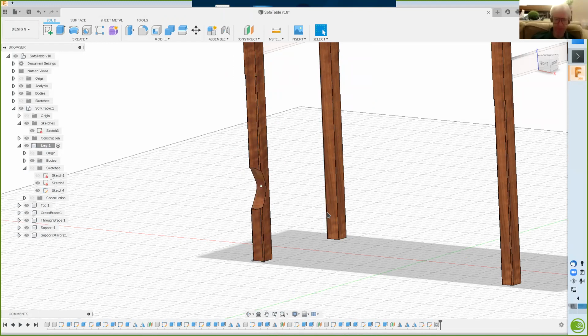Ideally, they would all be linked, and as you made a change to one, it would be reflected in the others. Is that what you're saying, Bruce? Right. Okay. So I've just done this really weird thing here. Yeah, there is a trick to this, and it's actually pretty easy. If you click on the thing that you just did, the hole, you can move it in the timeline such that it's before the mirrors. Oh, look at that. Way to go, man. It's all about the timeline.